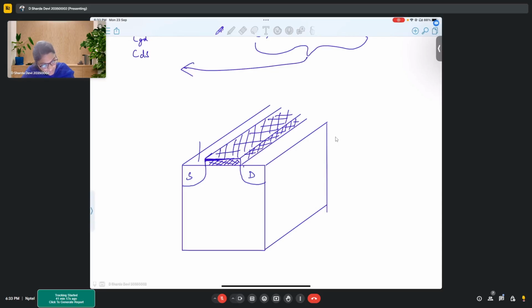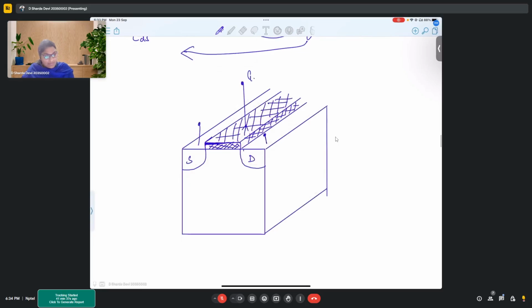And then we would have source, drain. Here you take the contacts. So here there will be the contacts. For gate you would take the contact from here. This is gate contact. Source, drain. Body you can take somewhere here, or you take it from far apart.